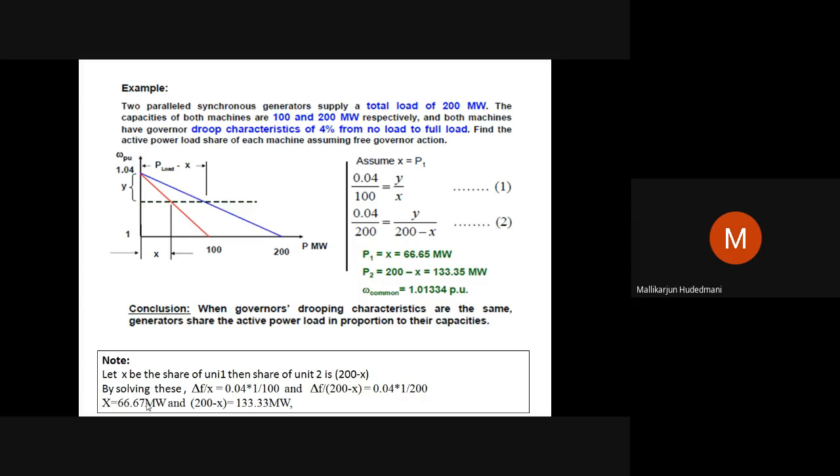The machines with a higher capacity respond higher by increment. Machines with a lower capacity respond lower. The other way, if there is a fault, the first gets affected badly, the other gets affected lesser. It means the reflection of the component is proportional to their capacity and characteristics. In this regard, machine 1 being smaller responds for a change of only 66 megawatt. The other is double that capacity, so almost double the value is going to respond. This is the solution we know from our earlier example.